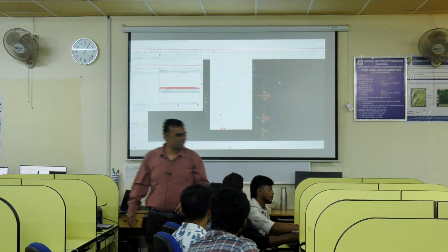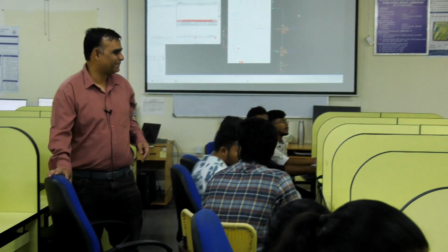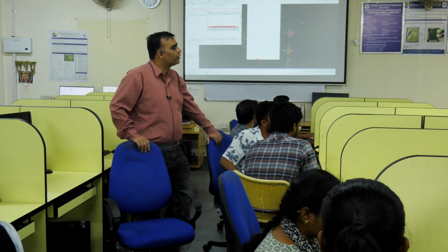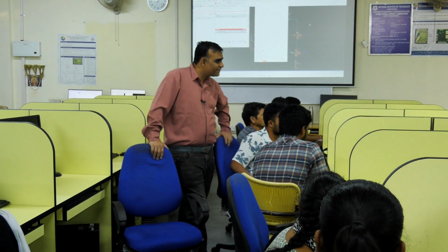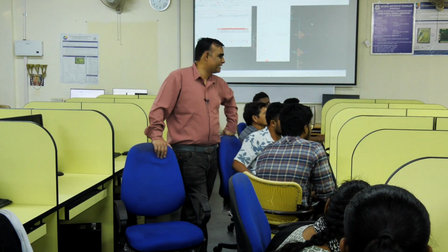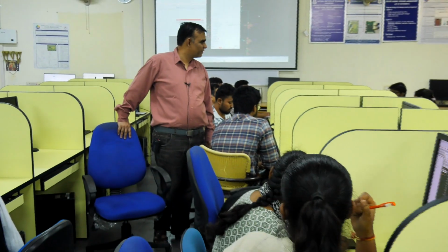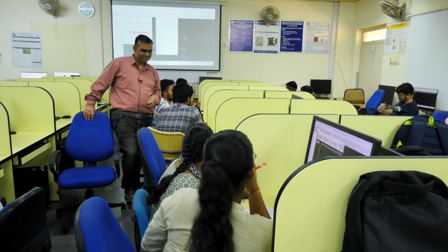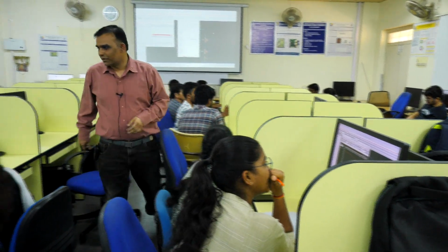It's a trick question. Again, what's the x-axis? So what's the unit of log? Precisely. So essentially, you cannot have a plot which is log of I, because I has got a unit. So you're essentially doing a plot of log I divided by 1 ampere. You're normalizing it. Volt per decade, you can say. So in 1 decade, how much it changes. So that will be the unit. Okay? Well done.